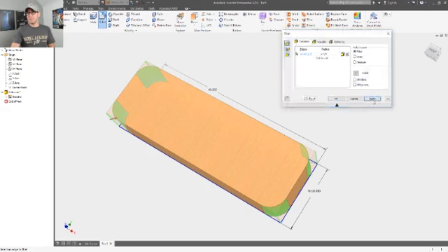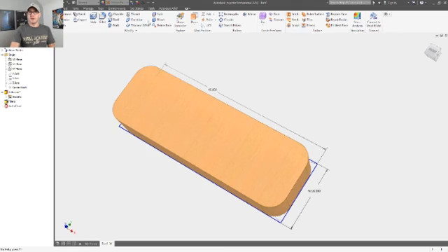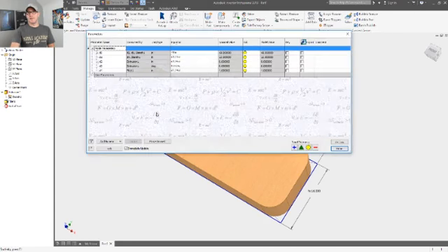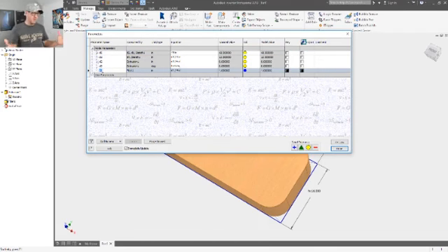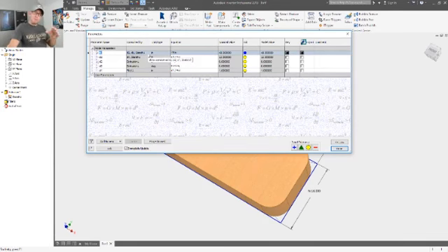And then the neat thing that happens here is when you go and look at your parameters, so when I go to manage and I go to parameters, you're going to see D0 through D4. Those are the only D values that we created. You can see where it gets used. So if you haven't been in parameters recently, and I haven't done a lot in parameters recently, but this consumed by is great. It shows you that D0 is used by D2, it's used by D1, it's used in Sketch 1. So it's a really easy way to know how it affects those different features that you're creating or any additional sketches that you're creating.